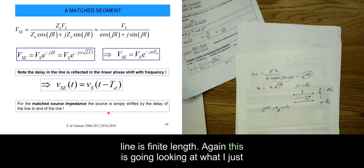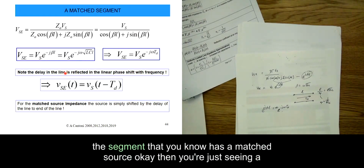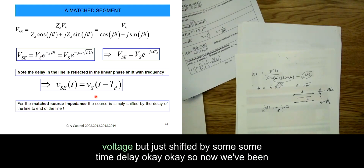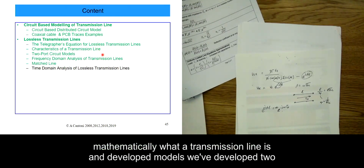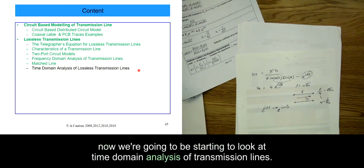So again, this is what I just said: if you have the segment that has a matched source, then you're just seeing a delay. At the end of the line, what you see is the source voltage, but just shifted by some time delay. Okay, so we've been up to here. We've started understanding mathematically what a transmission line is, and developed models. We've developed two-port models. We did a frequency domain model. We just looked at the matched line. So we've had a lot of good analysis, and we can solve a lot of stuff in the Laplace and the frequency domain. Now we're going to start looking at time domain analysis of transmission lines.